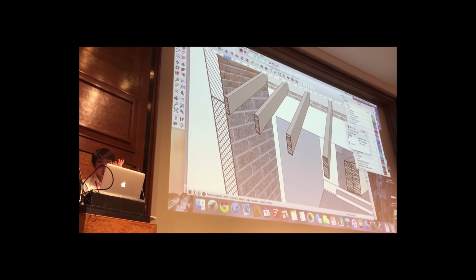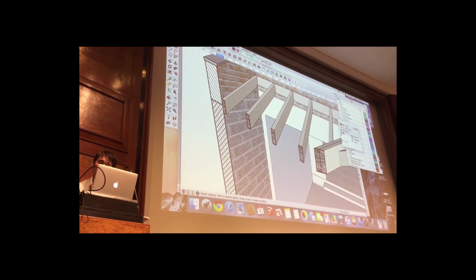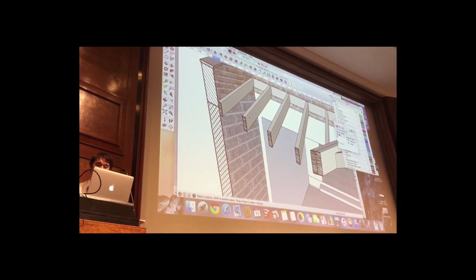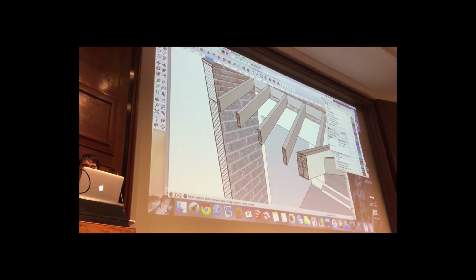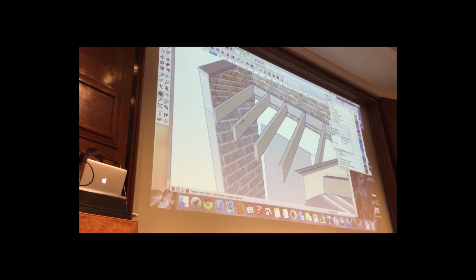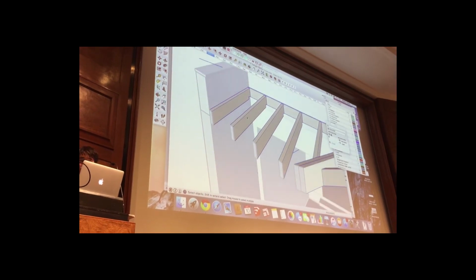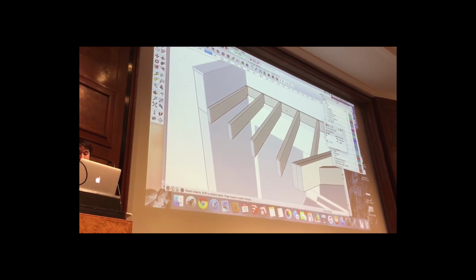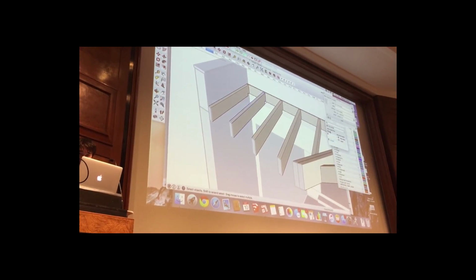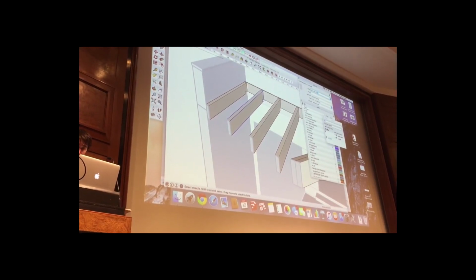So, again, timber. I know that you normally put in a cross for the material, but it's a bit tricky at the moment, and I'm told that the Skalp guys are working on it to get this working. You can do it. The best way to use Skalp, in my view, to get a really productive workflow, is to use, there are many ways to put hatches onto your object, but I always use the layers. So if I wanted to change the layer, I'll go to timber, material, finish, for instance. And I have a material layer set up for that.